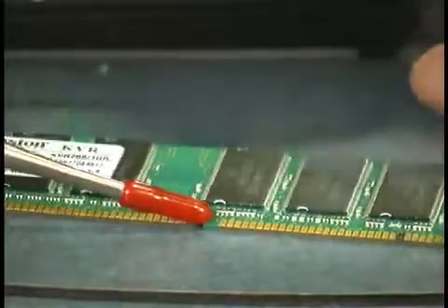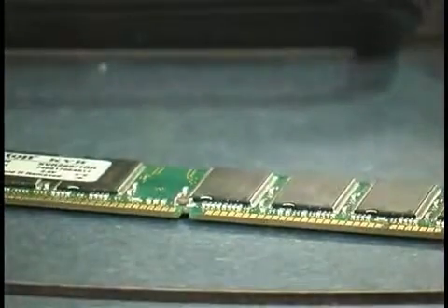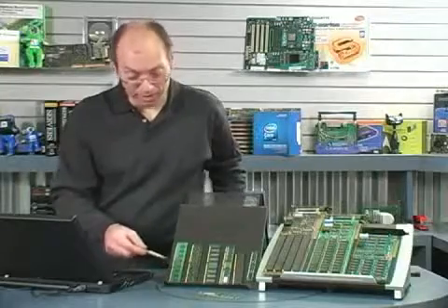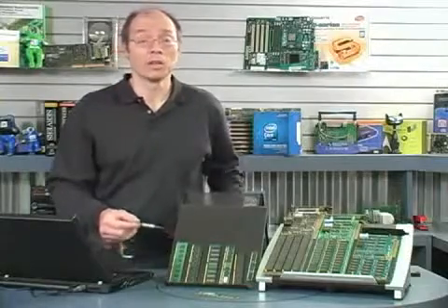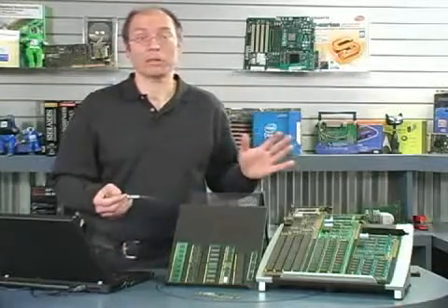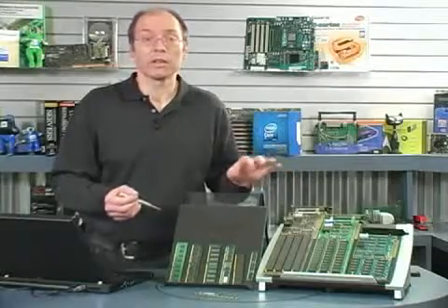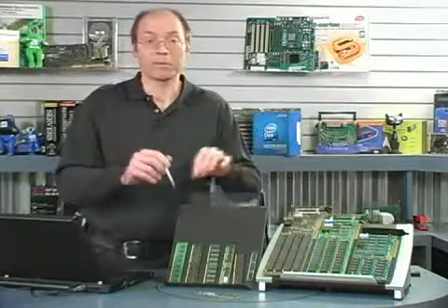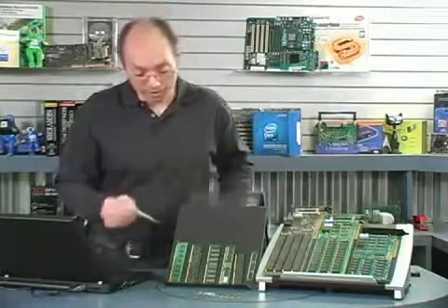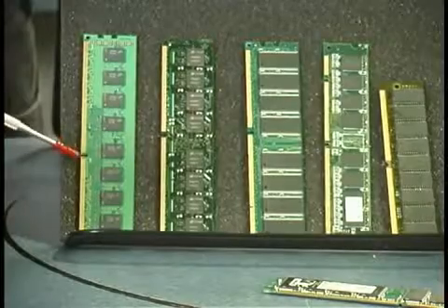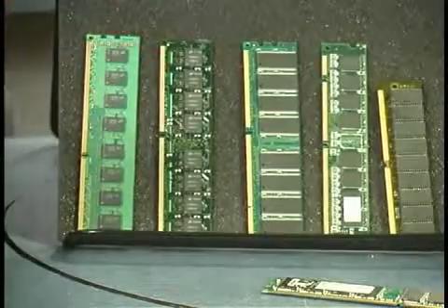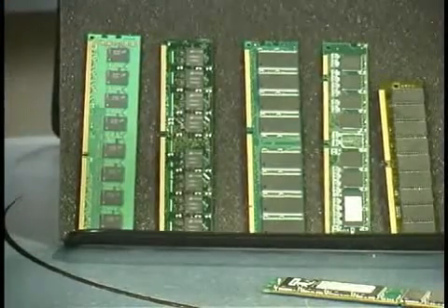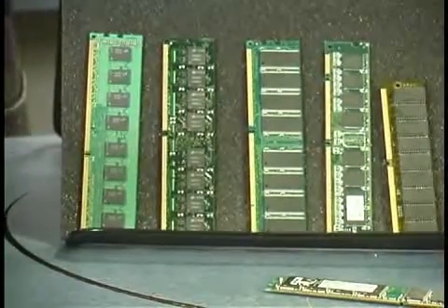Now, sometimes this can be confusing. For example, in the case of the DDR2 and the DDR3, they both have the same number of pins. They're both 240 pins, yet they're incompatible with each other. How do you make sure that the right memory goes into the right socket and in the right orientation? Well, if you notice, the notches on the DDR2 and the DDR3 are in different positions. So by altering the position of these notches, these keyways, they try to make sure that you can't plug it in backwards.